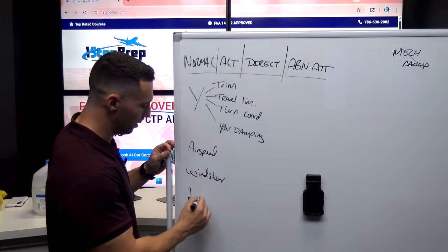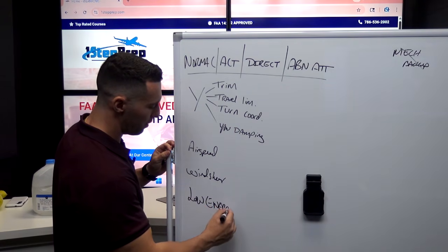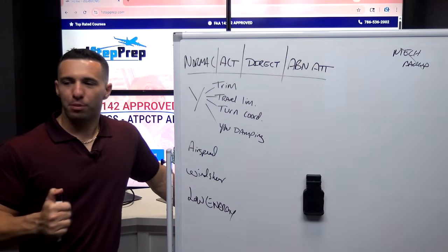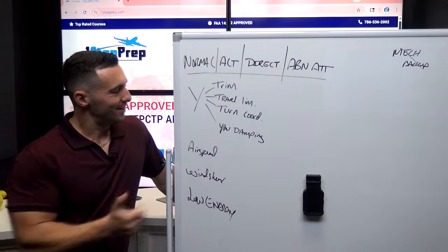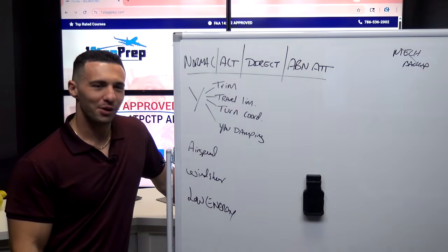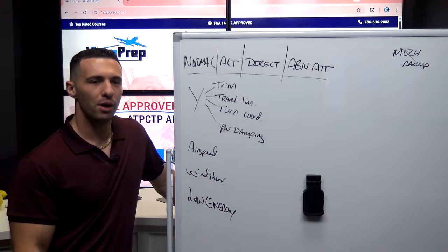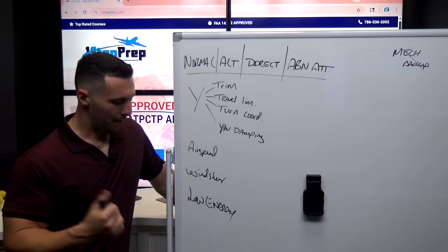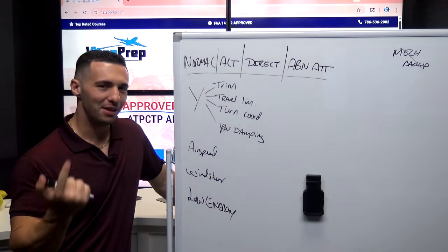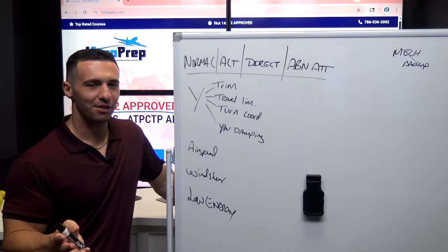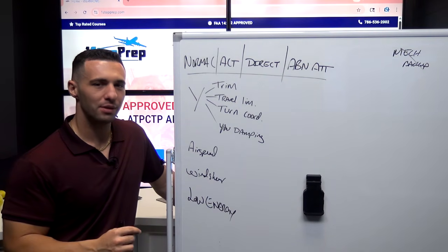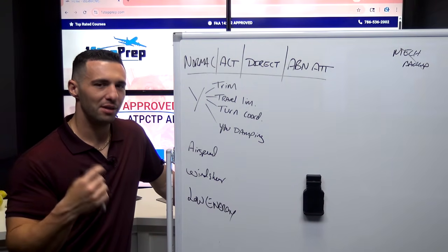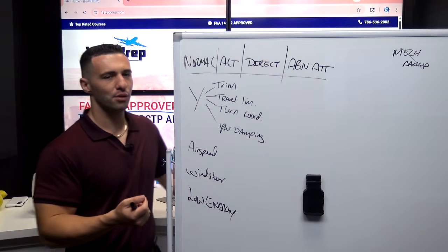And then the last thing we have is the low energy warning. All FAC provided. So we have the yaw inputs, the airspeed envelope, the wind shear alerts, and the low energy warning. The low energy warning, if you don't know, is basically where you hear "speed." You're only going to get this on approach because the flaps have to be in 2, 3, or full configuration. You get a little bit slow on the airspeed, and all of a sudden the airplane starts saying "speed, speed, speed." Sometimes we hear this in the circling approach.